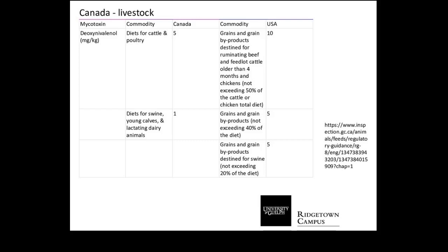And then mixing that pail full of sample and taking a 1 kilogram sample away for testing is probably important. Now, what I've learned is the labs are also splitting the sample mechanically first and not grinding the whole thing. The problem is it ends up taking more time, and there's more flour to dispose of.